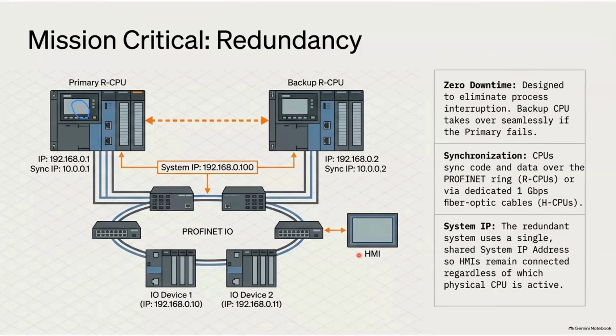Usually, most cement plants or critical units that work 24/7 keep these redundancy systems, primary and backup, and both will be given a particular address. If we have to modify any primary module, then we can upgrade it. We can keep it under maintenance for about 1 month or 2 months or 3 months, and during this period the backup CPU will keep running. As soon as this is done, we take it into the production environment, and the backup will also be updated in such a fashion.